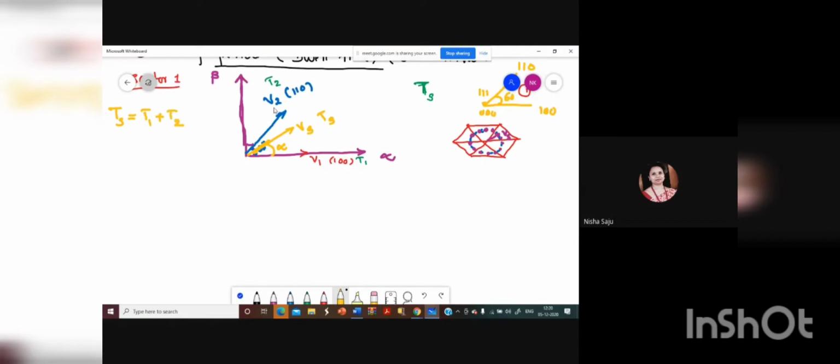Then in addition to that, in that particular sector, you will be having two zero states, 1 1 1 and 0 0 0. This is your V1, this is your V2, and this is your V0 because it is representing a voltage. So you are having two zero-state voltages that will be switching for a period. Even though it doesn't appear in the output voltage, you have to put it as equal to T0 because you have to take that order. Then only you will be getting the full sector. In order to get the full first sector, you have to take this point also. Then only you can close it, right? So you will be having 0 0 0, then 1 0 0, 1 1 0, then 1 1 1.